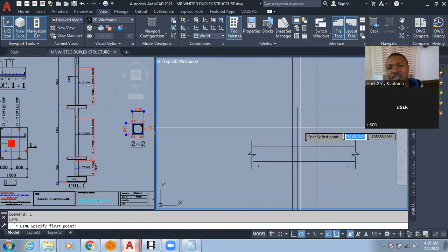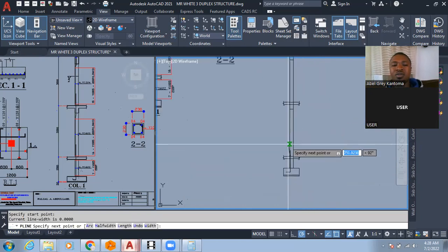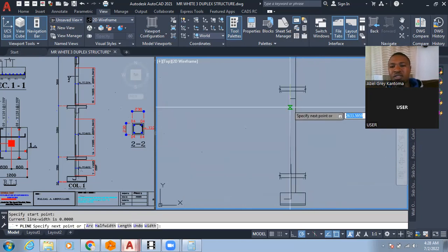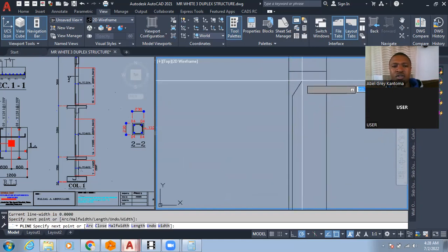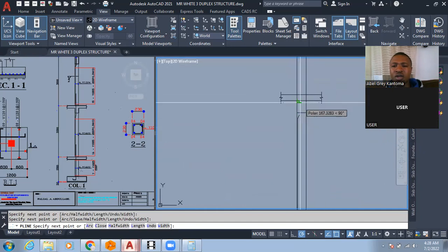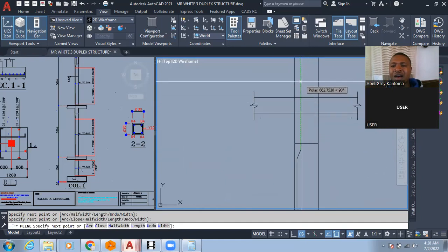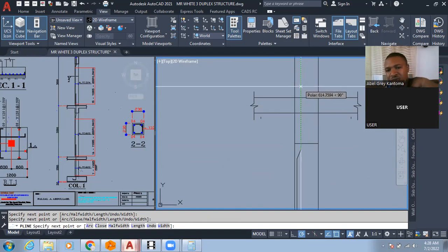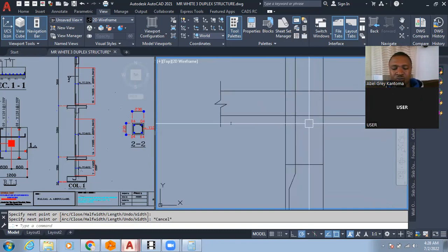Please, site experience matters, design experience matters. All this experience will help you to be able to come up with your design. This one will shift a bit like this because you are going to have your reinforcement from the column entering the beam. Okay, because here you have a beam, entering the beam. That is why you have this one staggering this way.